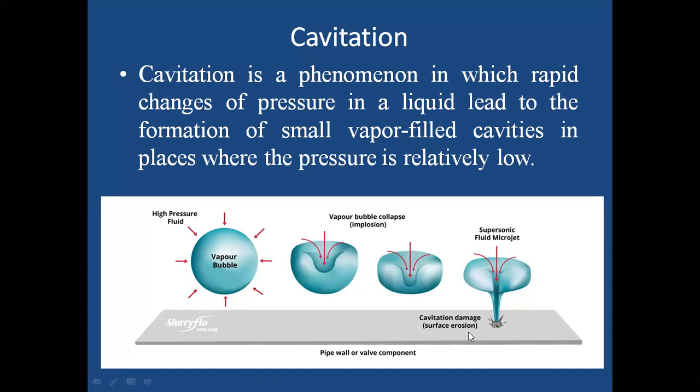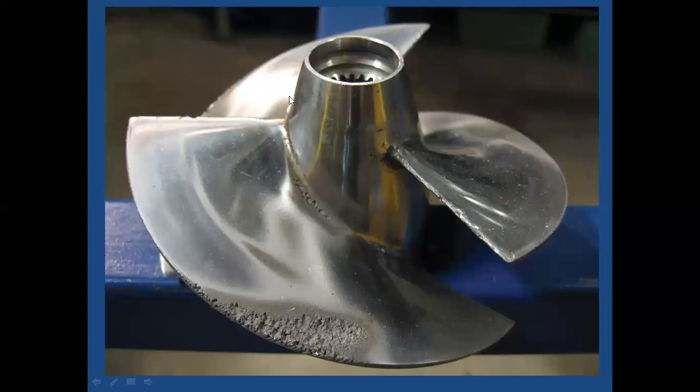So in this place, there is a lot of pressure involved. Cavitation will make these parts get damaged. Okay, so I'll show an image where cavitation plays a vital role. See, this looks like an impeller. It's a turbine impeller or a turbine blade, which is axially curved. Here we can see the cavitation part. This is due to the continuous, high speed jet.